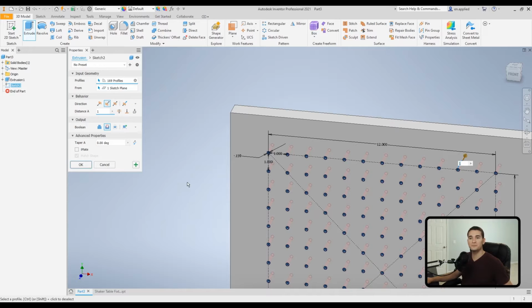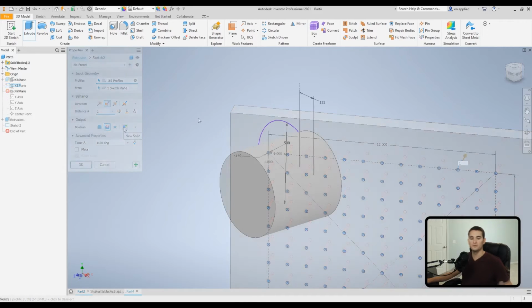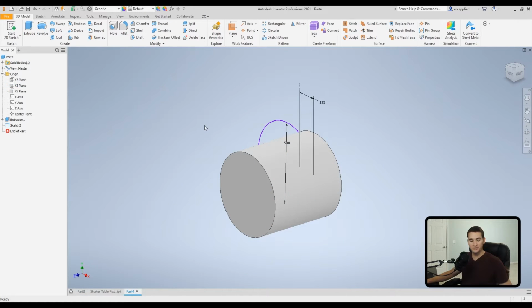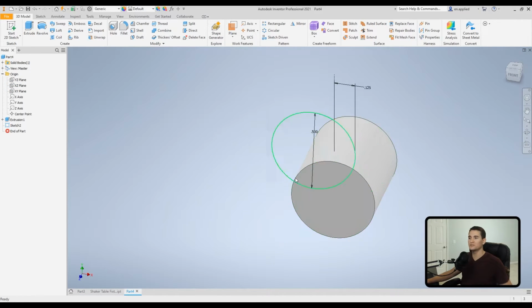I took a couple of steps back, and now we're back in our window right before we created the cut. I wanted to explain these other 2 Boolean operations that we see in here. And then of course we have our drop down with our selector style, so we can do the same sort of drop down or icon view. But to illustrate intersect and new solid, we're going to jump into a new part. Okay, so for our intersect Boolean operation, I went ahead and drew up one cylinder here of diameter 0.5 inches.